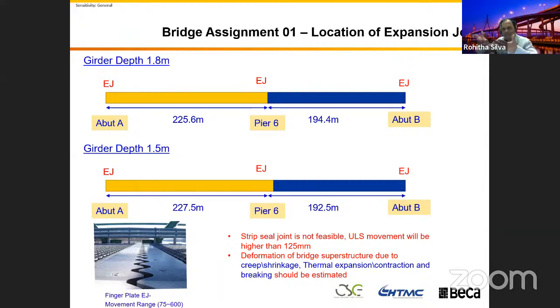Even when you apply that in the model, you can calculate. You will see that in the next, after next sessions, how you're going to develop that. You can calculate this deformation. You need to be really mindful. You need to calculate this deformation in the central bridge, because when the bridge is expanding, these two are pushing, this joint will be closing.